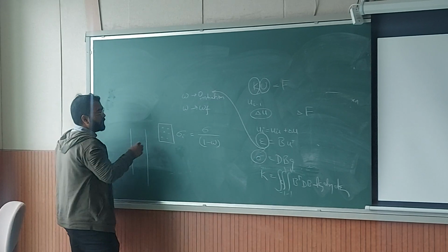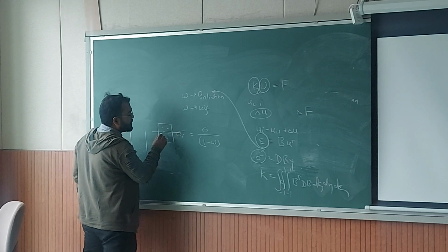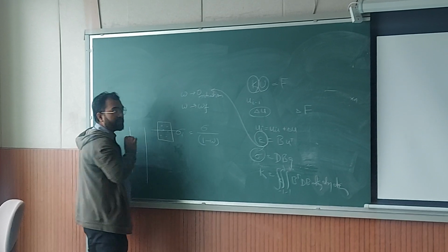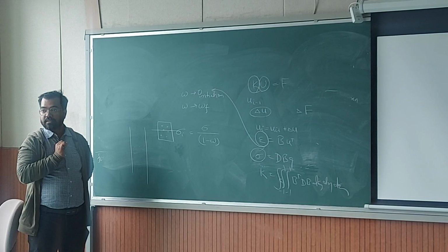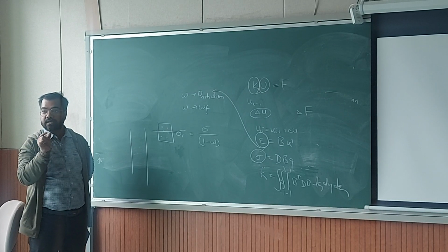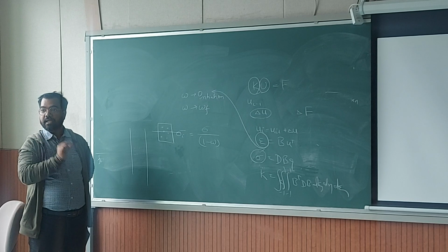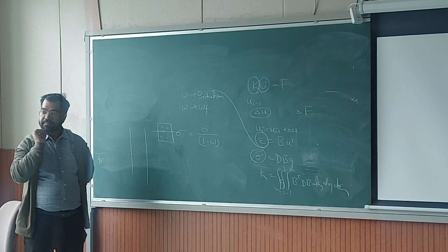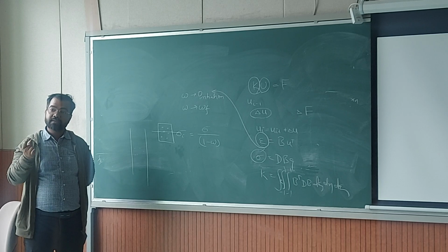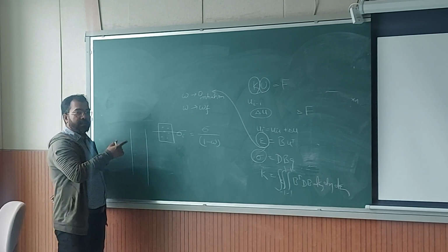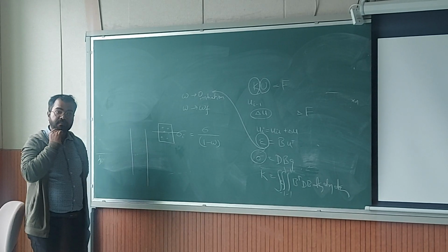So when you cut across a plane, then you are saying that certain area must have been decreased because of the presence of these voids, right? And that area decrement you are taking as omega. Okay? And then you are correcting that area by 1 minus omega, and you are correcting or updating the stress value.